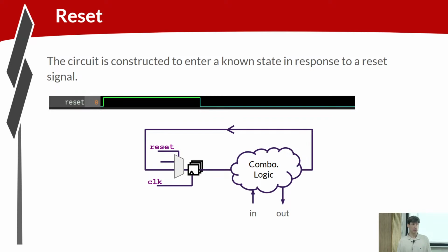Often we use a negatively asserted reset signal, reset N or reset bar, or whatever you want to call it. That's kind of arcane based on, I don't know, historic constraints. With TL-Verilog, with MakerChip, we use a positively asserted reset, design all our circuits that way.